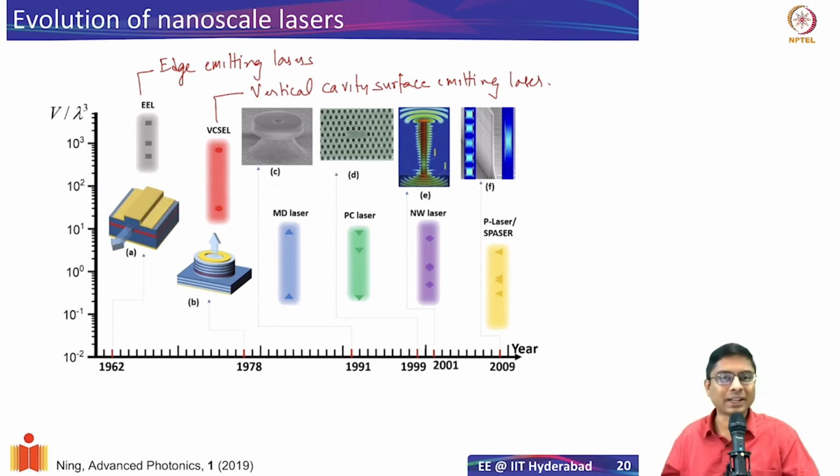So scientists invented the idea of a vertical cavity. They put a mirror at the bottom and the top, and the gain medium in between. It's also interesting how these mirrors are constructed. These are what are called distributed Bragg mirrors, DBRs. Using photonic crystal ideas, we can design these structures. It's simply alternating layers of different dielectric constants, so that at a particular point there's a peak reflection. You put two different distributed Bragg reflectors that way, and in between you put a gain medium, schematically shown here, and then you have a lasing cavity.